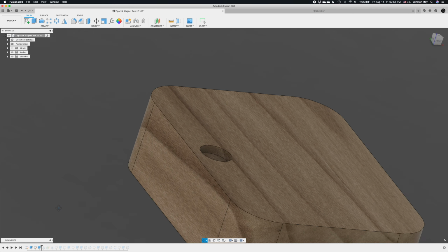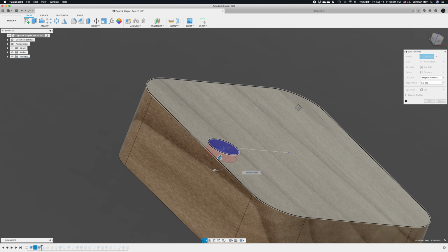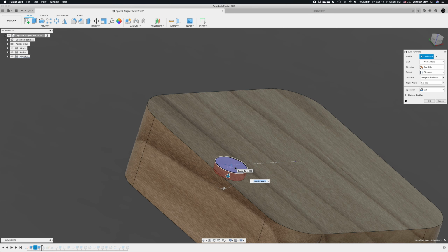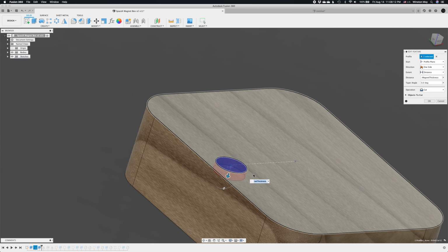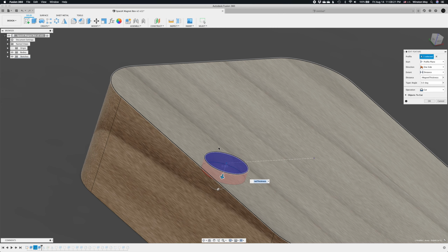The extrude function uses the magnet thickness, which is actually a couple thou thicker than the magnet actually is. It's a 16th inch magnet, but since it was probably manufactured in China, it's probably a 1.5 millimeter magnet. But you want this pocket to be a little deeper than your magnet actually is, so your magnet isn't flush with the top surface of your box. That means when you put the lid together with the base, there's actually a small gap between the magnets.